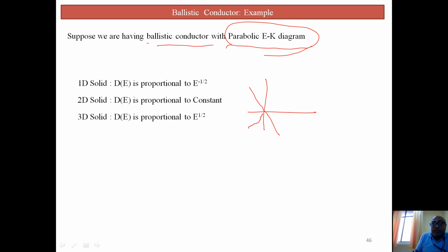this is a very special case for graphene, where it is linear: energy versus K, the momentum vector. But for silicon, it is kind of a parabola. Only thing is that you may have a valence band here, because it's an indirect band gap, and you have multiple subbands. And the philosophy of subbands you already know. That part we have studied.